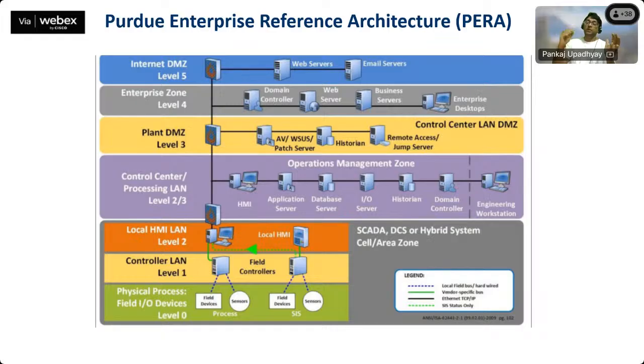If one system gets exploited through certain vulnerabilities, it can be used to exploit other systems. But with proper segmentation, suppose your level 4 system is exploited by an attacker, we do have a firewall, we have segmentation, we are not allowing every traffic here, so we are protecting the lower level architecture.